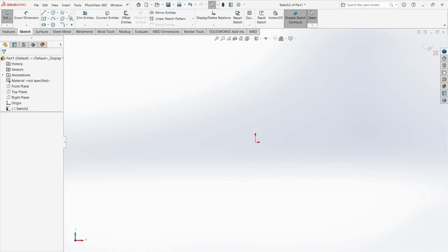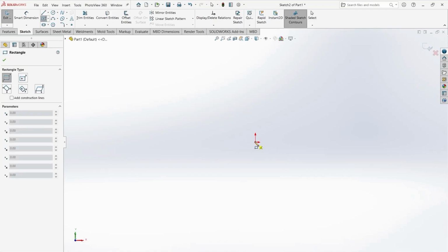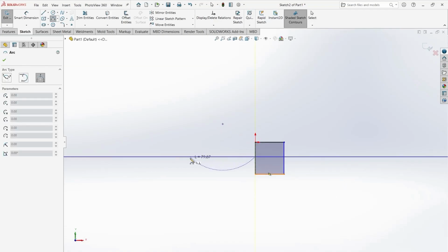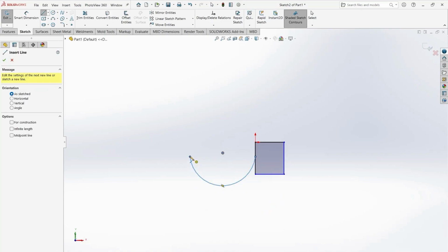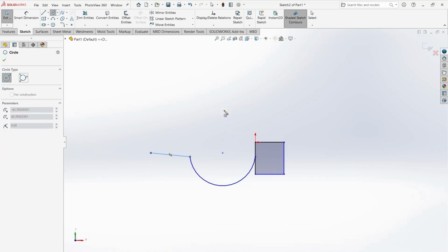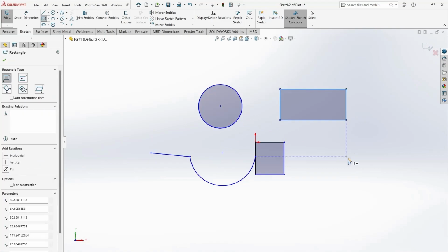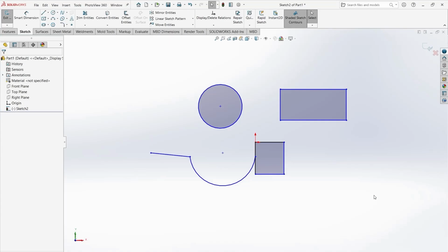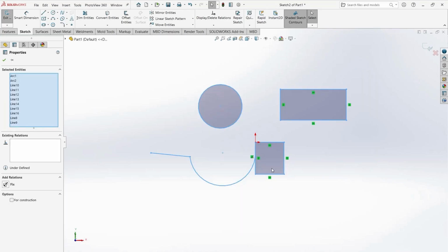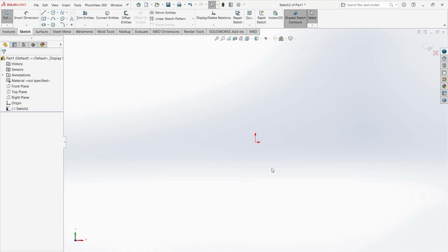Instead of directly going and selecting whatever you want from the upper side and then pressing escape, selecting it like this increases your speed a lot. Suppose again if I choose line, now if I choose circle, now if I choose rectangle, this way your speed increases a lot faster. And I will always recommend you to keep the left hand, one finger on the escape button, because you always have to press escape whenever you exit, and that increases your speed a lot.